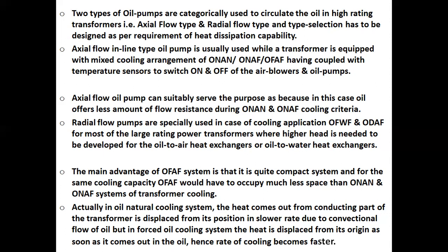Radial flow pumps are specially used in cooling applications OFWF and ODAF for most of the large rating power transformers, where higher head is needed to develop for the oil to air heat exchangers or oil to water heat exchangers.